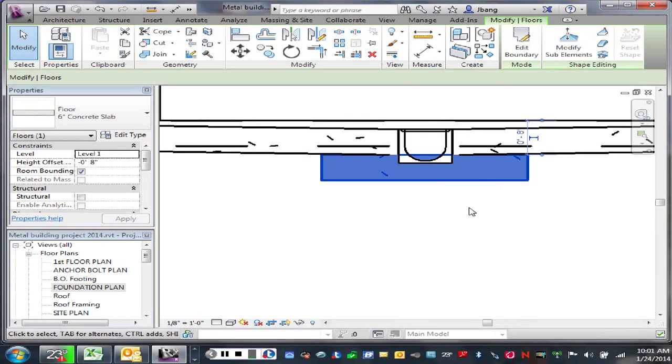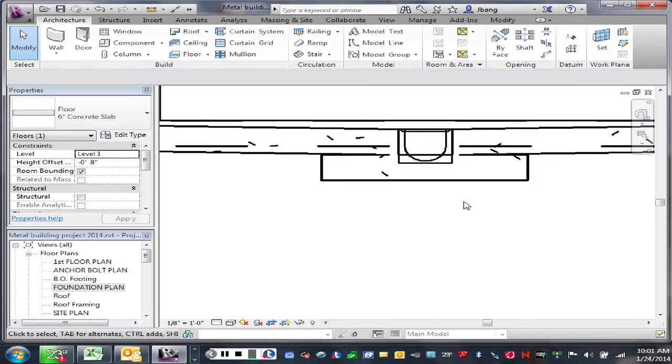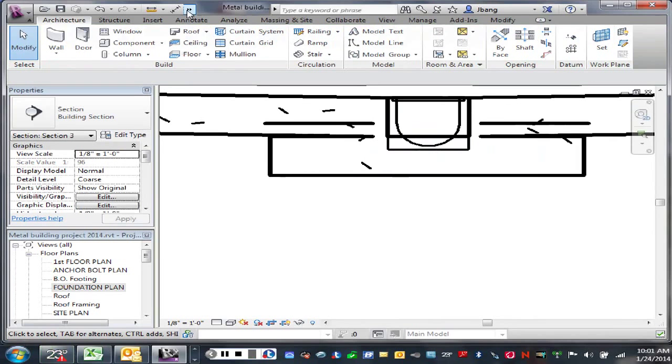Yeah, the concrete would have to go down and around it, so the whole drain is encased in the concrete. So it should go past the drain, basically. Any specific distance, or a couple inches? I would say if the slab is 6 inches, you'd want to go 6 inches outside of it on each side.